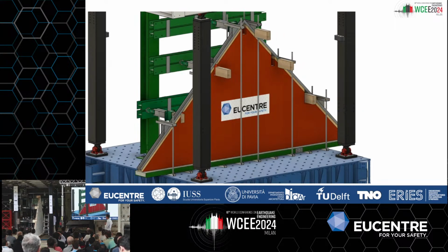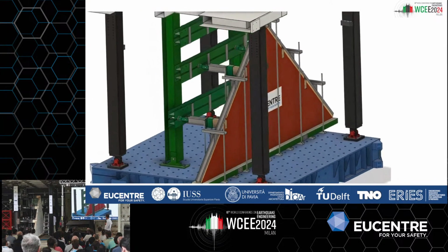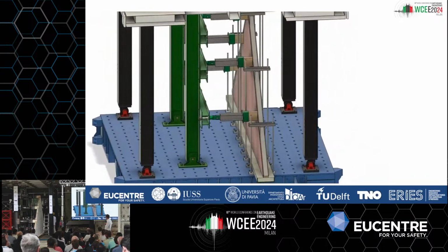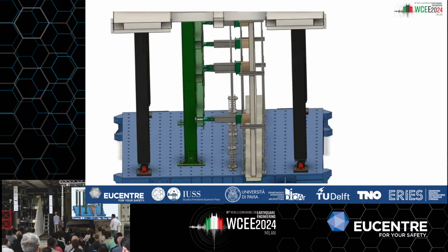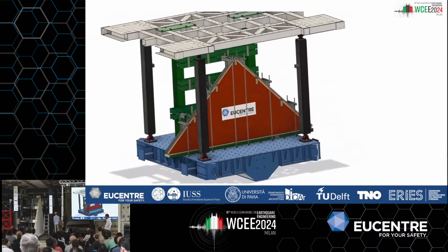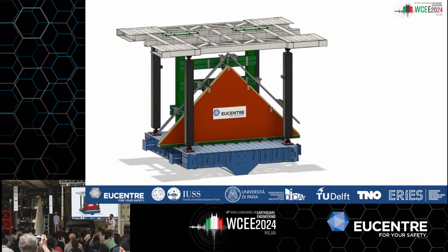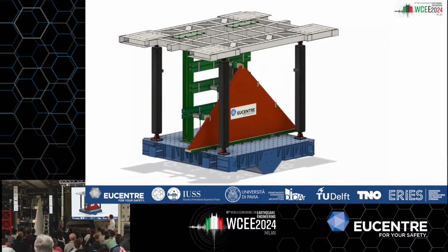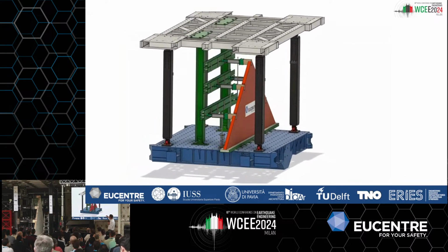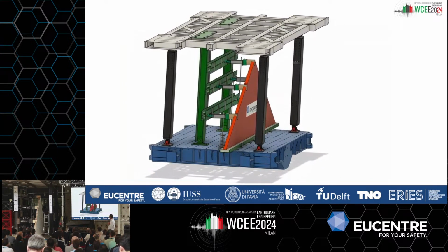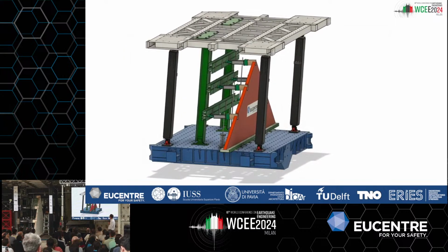Insert the timber beams and load the timber beams via springs, wide springs, because with the small elongation that we will have due to the motion of the setup, the force remains quasi constant. Once the springs are loaded, the wall is safe, so we can unpack the wall, and this is the system working.